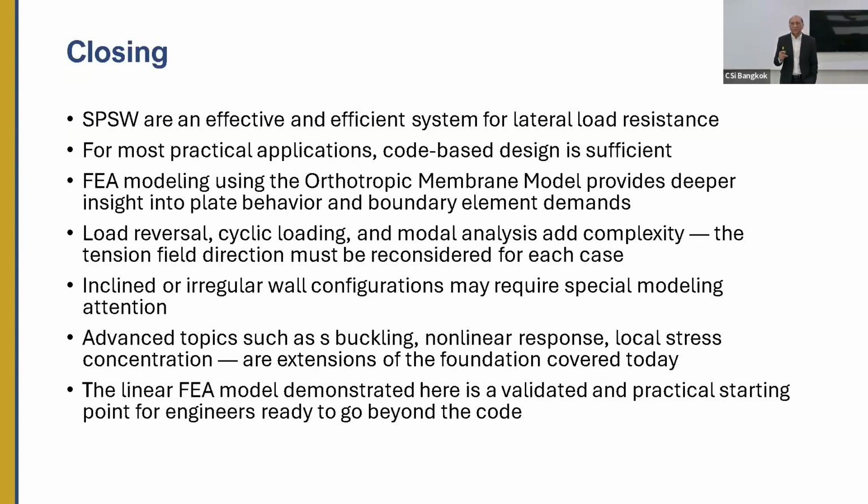Load reversal, cyclic loading, and modal analysis add complexity to the analysis, and you need to handle them either by using multiple elements or multiple models combining the results. So it's not a very easy thing to do, or we go to nonlinear, which of course can capture these responses. So we include the irregularities, and especially if you have openings in the walls, special irregular walls, or the panels are not rectangular, then the code equations may not be sufficient.